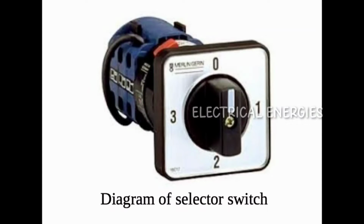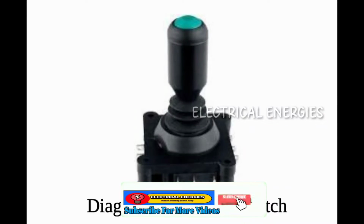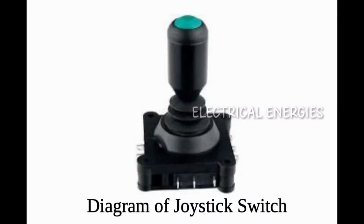Number 4. Joystick switch. The joystick switch has a lever that is free for motion in more than one axis. Think about the analog button in a joystick, where you get to rotate it in multiple directions without restriction. The flexibility is not quite at that level here, but it gives you an idea. One or more than one switch contact mechanism out of several gets actuated, and this is dependent on the direction that the lever is pushed. At times, this is dependent on how far the lever gets pushed.